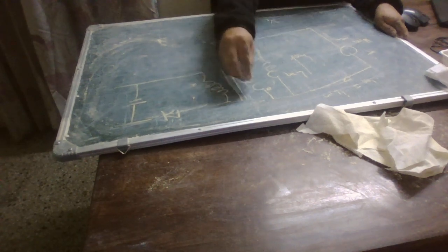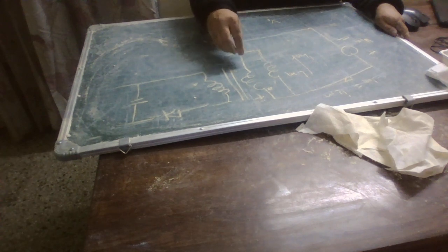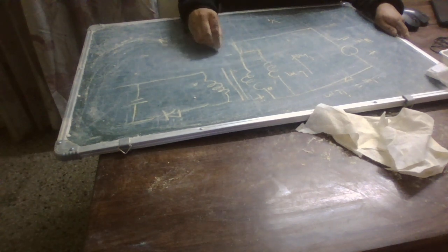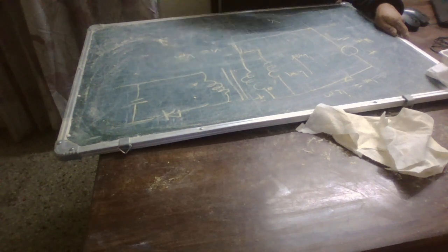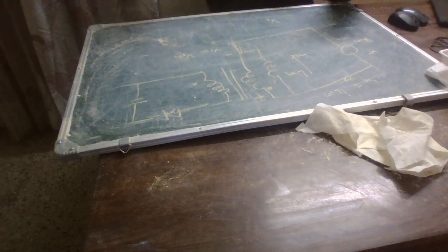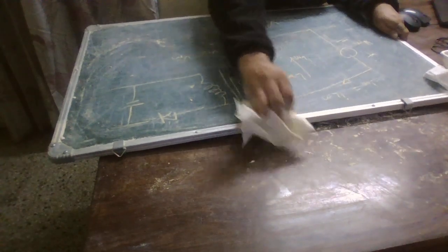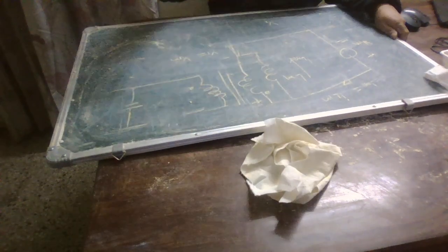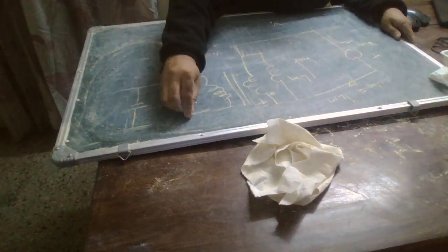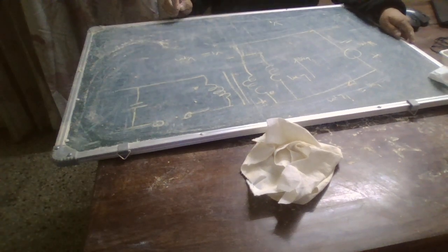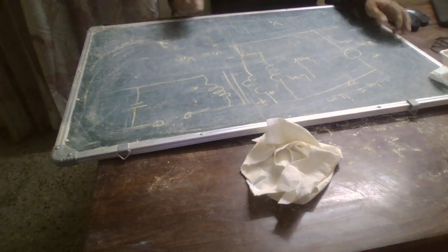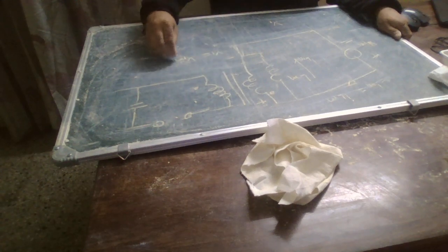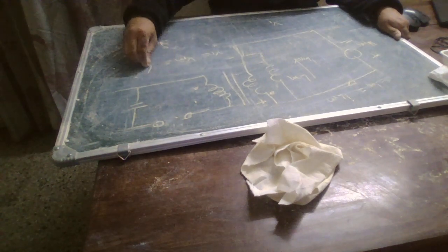This voltage, plus minus, would be equal to, let's say, V1, and this would be equal to V1 only. Now during an on period, I forgot, one mistake was done. During an on period, this would become open, this would be reverse biased. So I can even remove the diode here, and during this T on period, we can say V1, the voltage across this primary, is equal to V input.